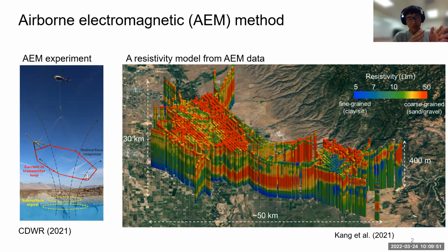Okay, so that's the typical AEM experiment. The induced voltage that we measure depends upon the type of survey. Sometimes you could use a frequency domain system or a time domain system. The one that I explained was a time domain system, where we have multiple time channels of data from which we can obtain information about the subsurface resistivity. The early time usually includes information about the near surface, and the later time includes information about the deeper part. By analogy in frequency domain, high frequency data contains information about the near surface, and low frequency data contains information about the deeper part of the subsurface.